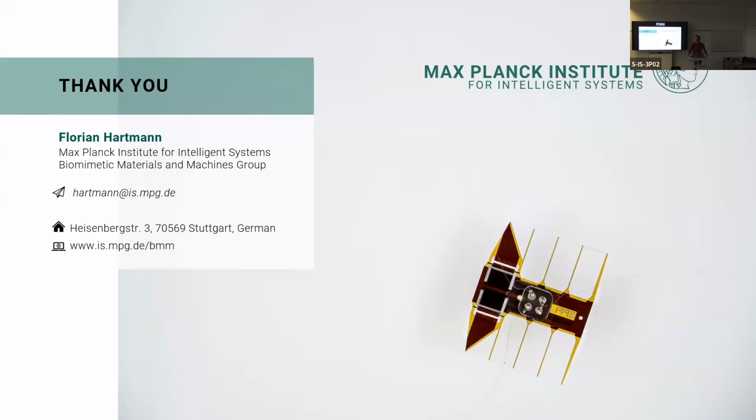Yes, I can. If you take, for example, a silicone rubber, then you will have a material that is stable at 300 degrees at least. So quite high temperature stability. It also works at negative temperatures, if you design the material right, with materials that work also at minus 40 degrees Celsius. What you need to consider if you work with polymers, like plastic, rubber, is that their stiffness is also changing with temperature. That will never change because that is how the physics works in those materials.